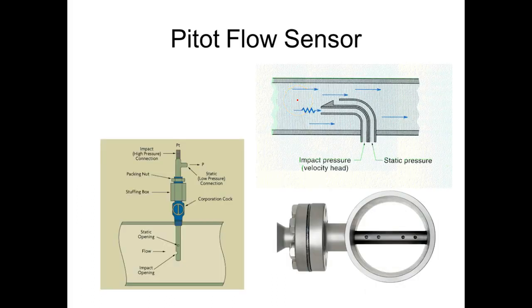These are called pitot static. So what we have to do, we always have to have a reference that we measure our pressure from, right? So you notice both those had a high pressure and a low pressure. It's just like when you make measurements inside your circuit, it's always referenced to two things, right? You understand? You got two meter leads. If you only stuck one of them in there, you have no reference, and your meter would be very, very confused.